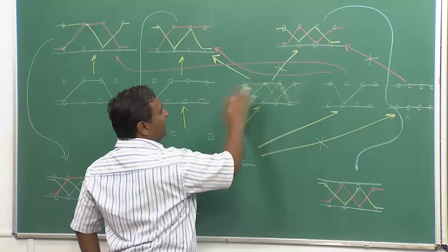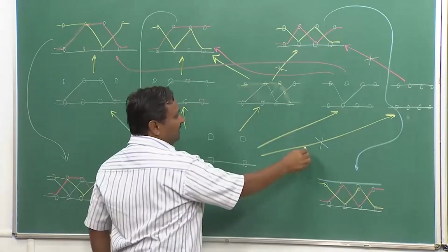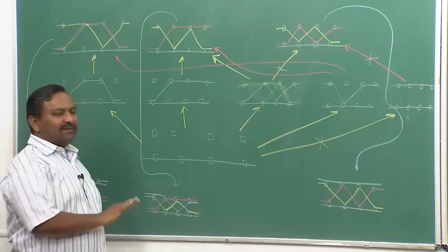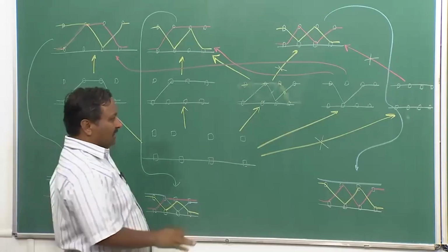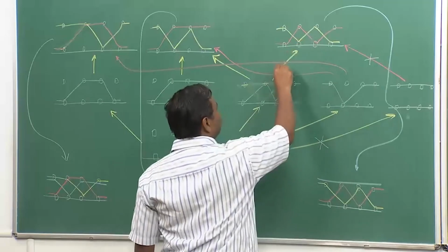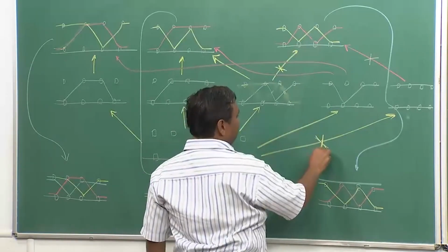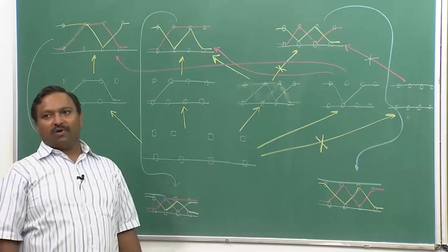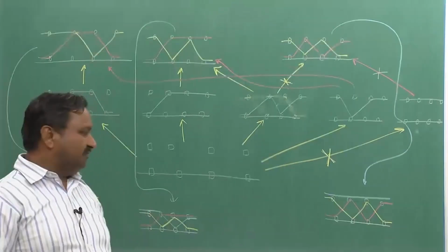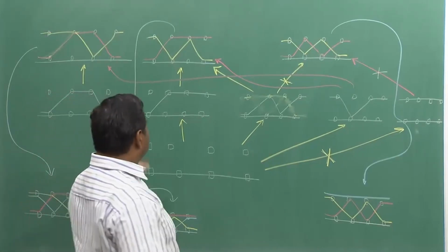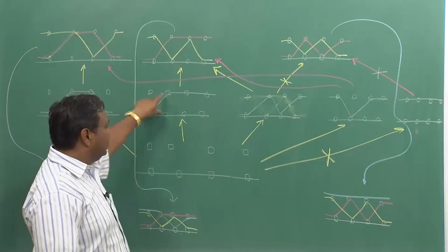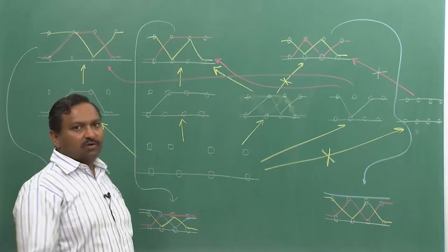So, all kinds of third connections can be set up. So far I am not permitting these two transitions. So, you will never see blocking if you avoid from here to there and from here to here. So, these two transitions, if these are being avoided, your switch will operate as a wide sense non blocking switch, and this is how actually we prove that a 4 stage system with 2 binary blocks in each stage will be a wide sense non blocking switch.